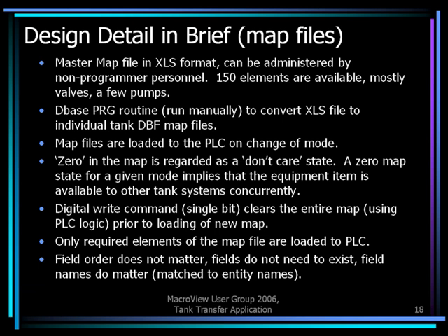It's very quick. And within the map files, the order of the fields doesn't matter. So the structure of the map file matters, but the way you define it inside the DBF file, the way we've put it together, means you can put the fields in any order. The field names matter, but the order of the fields within the map file doesn't matter. So if you decide you want to insert new valves and you prefer to insert it halfway across the map for reasons of neatness, or that's the way you'd like to represent it, then we don't hold you to putting it in a certain place.